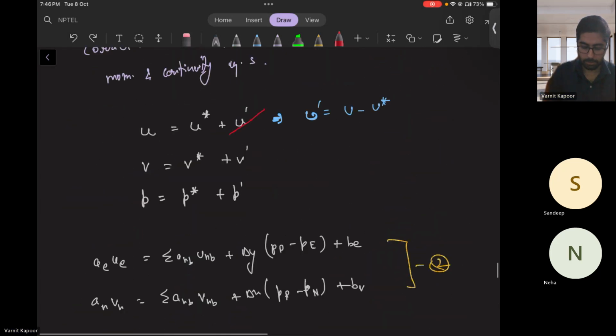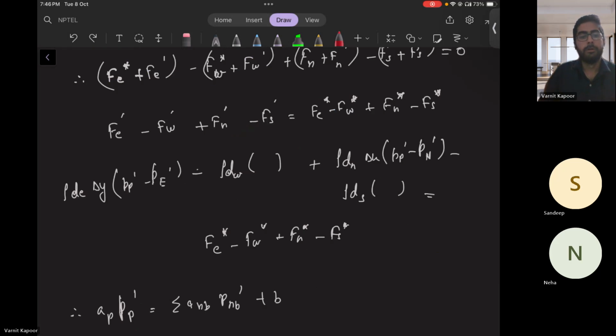As I said earlier as well, it is not the absolute pressure that matters, it is the pressure gradient. In incompressible flow we do not have any equation like the ideal gas equation or equation of state where the absolute pressure appears. We have pressure gradient equations. So in the incompressible flow equations, only the gradient of pressure matters. Even if your P dash keeps changing or is a constant value, it does not affect your solution. It is the pressure gradient that should affect it.